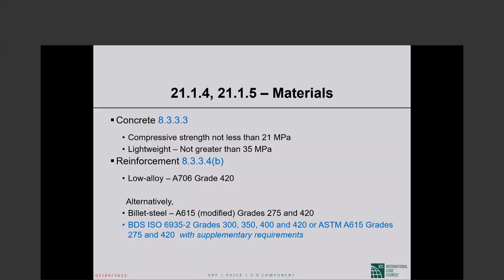Okay, concrete, normal weight concrete, there is a minimum strength of 21 MPa, which is slightly higher than the 17, I think, which is the absolute minimum anywhere. That I don't know is anything to discuss. Concrete of that strength is not difficult to find anywhere anymore.